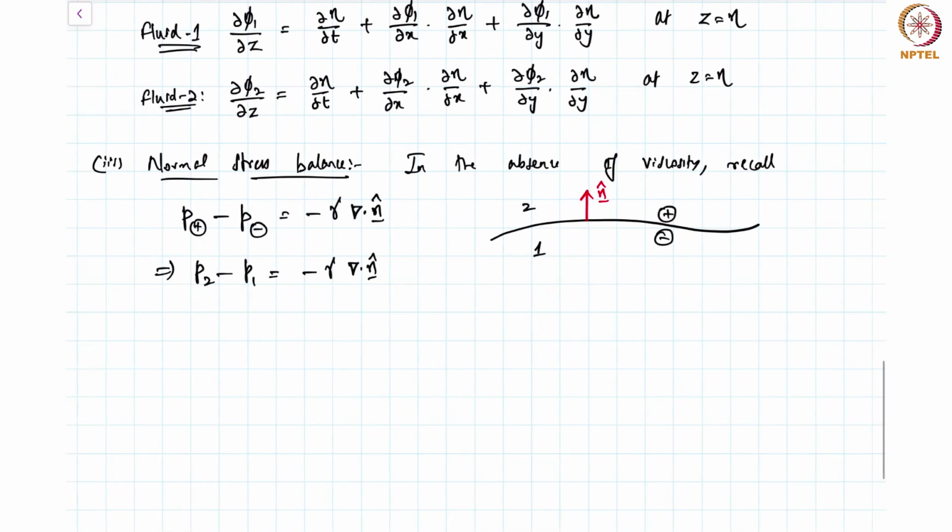Starting from Euler's equation, we can derive an energy equation, and we now have a time-dependent Bernoulli equation. I can apply this because it's an inviscid irrotational flow, using the time-dependent Bernoulli equation.